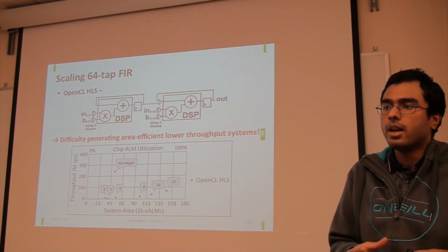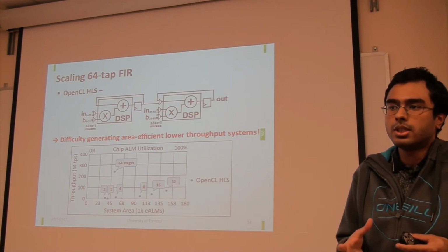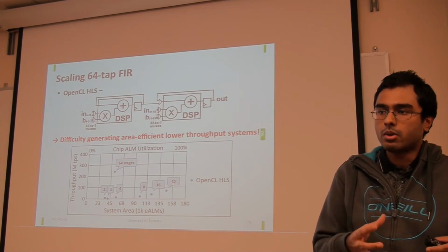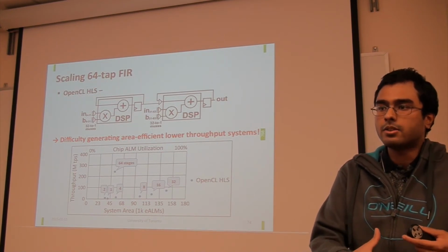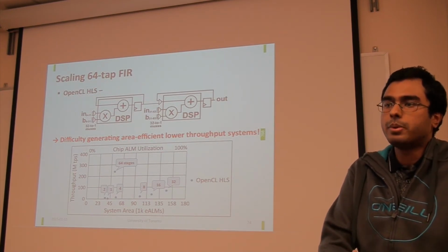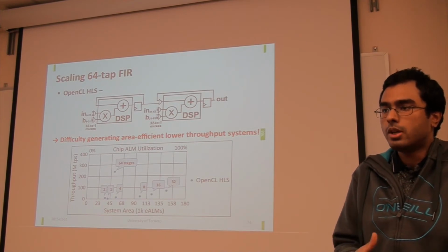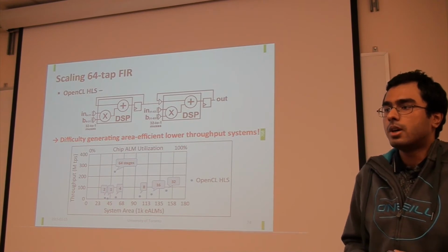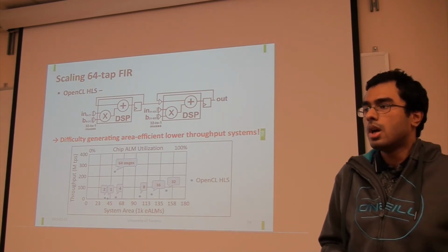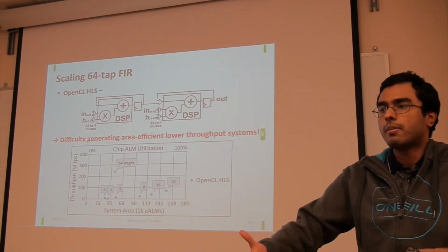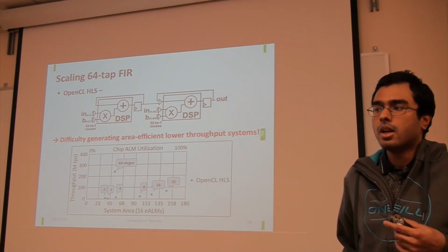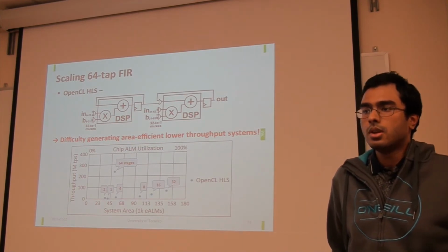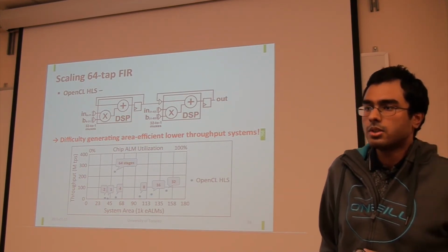The main advantage of using the tilt overlay as opposed to a fully spatial compute pipeline is that it will use significantly less compute resources to perform that computation. The throughput will be a little bit smaller because of that as well. But the main advantage is to reuse the compute resources on the FPGA device. Does that sufficiently answer your question?